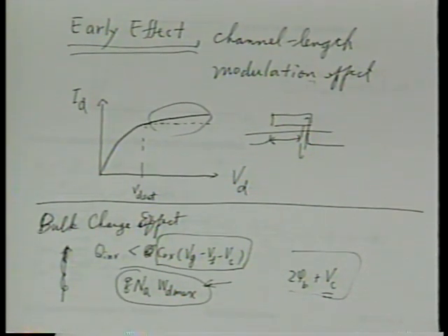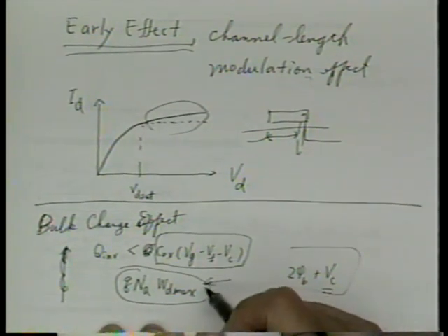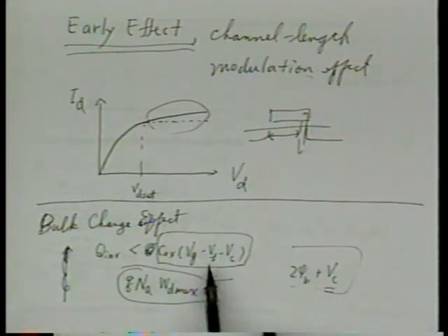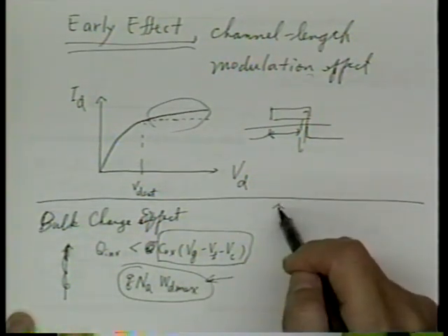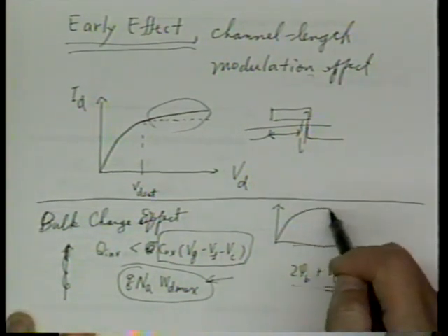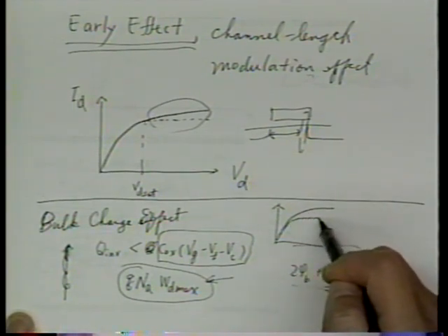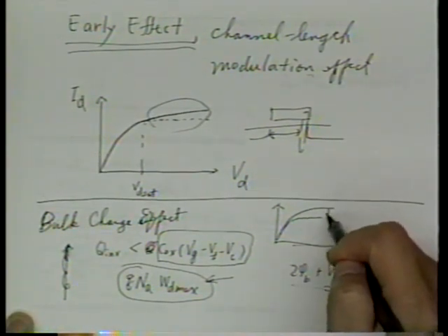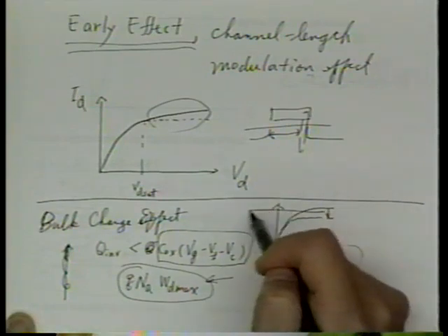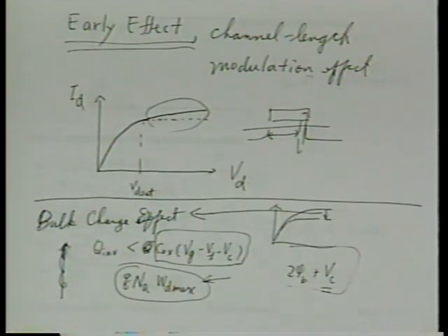Right? We talk about here today that this actual band bending goes beyond 2 phi B. It's for this reason that we cannot just use the fixed VT. All right. So the phenomenon is pretty complicated, and by doing that, we are going to end up with an IV curve that's somewhat lower than without considering it. This effect is called bulk charge effect.